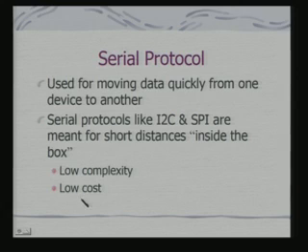And in fact, that is precisely the reason why I2C, SPI, this kind of serial bus protocols have become popular and are widely used in embedded systems. The whole idea is low complexity as well as low cost, and it is meant for short distances inside the box itself. Okay? So, it is not really on chip. In fact, we can have it on chip as well, but the typical use is within the box. That means, maybe connecting a PIC microcontroller with another device.